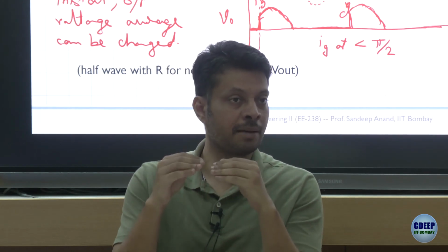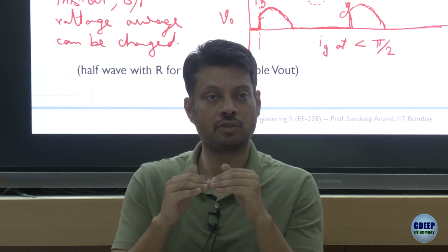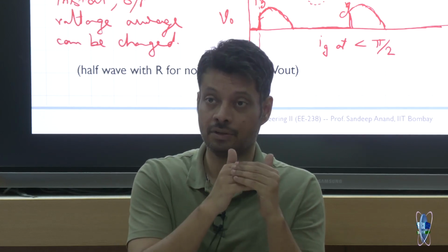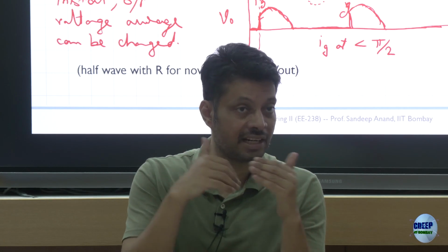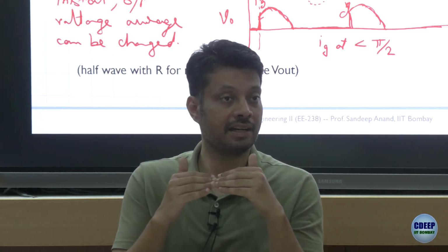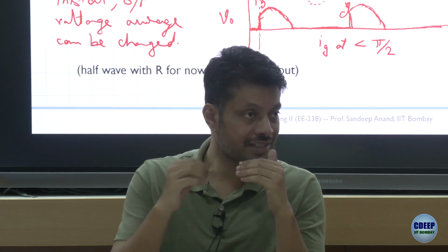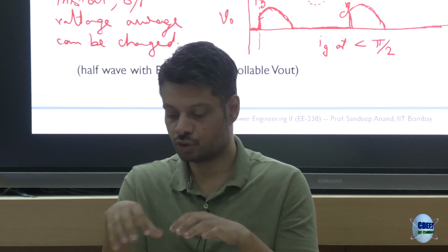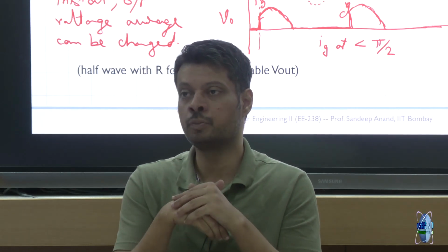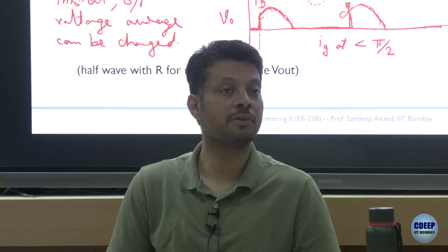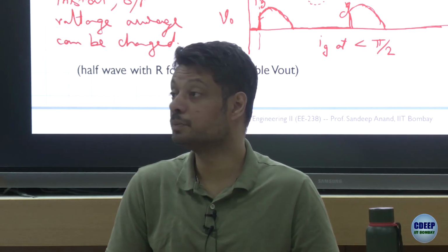The ignition, the generation of the arc, cannot start when your voltage is negative, because the electrons will not start flowing. Once they start flowing, then it doesn't really matter. So can you now draw the output voltage waveform? This could be a quiz question.